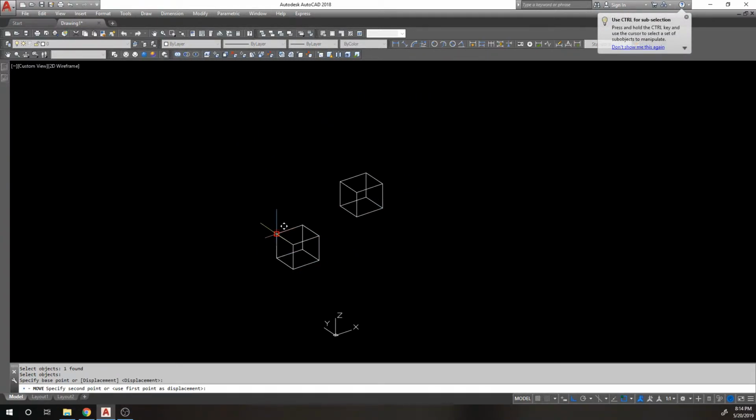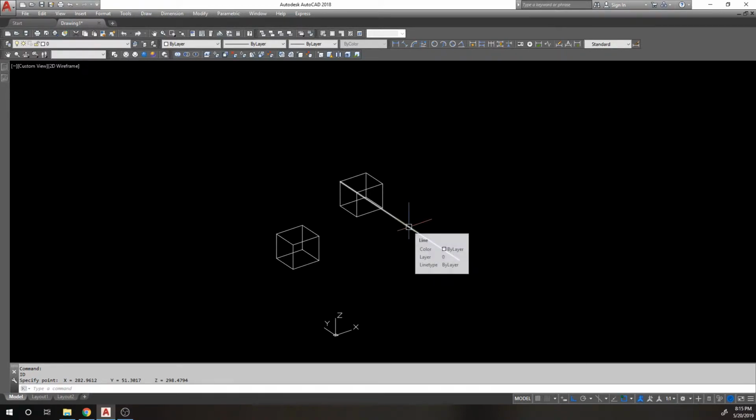When I move this box from here with the dot X over to here, I'm saying that whatever the coordinate is of this is an X coordinate. I haven't shown this command before, but this is the ID command. An ID will show you your coordinate in space. Okay. If I put an ID on this coordinate, they're all weird coordinates because I haven't put a grid or used specific coordinates. This is my X coordinate. Okay. And what I'm saying is I want this coordinate, which is totally different, to match this line at that coordinate.